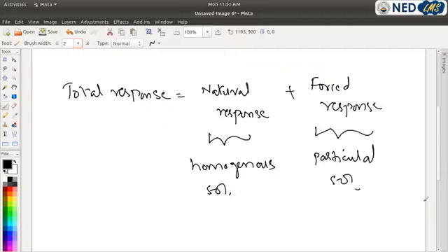Natural response of the systems describes the way the system dissipates or acquires energy. Hence, this response is dependent on the system and not the input. On the other hand, the forced response of the system is dependent on the input applied to the system. For a control system to be useful, the natural response of the system must eventually approach zero, thus leaving behind the forced response only.